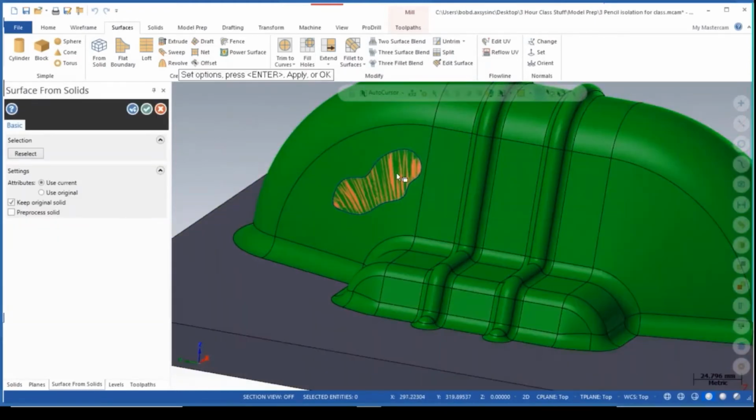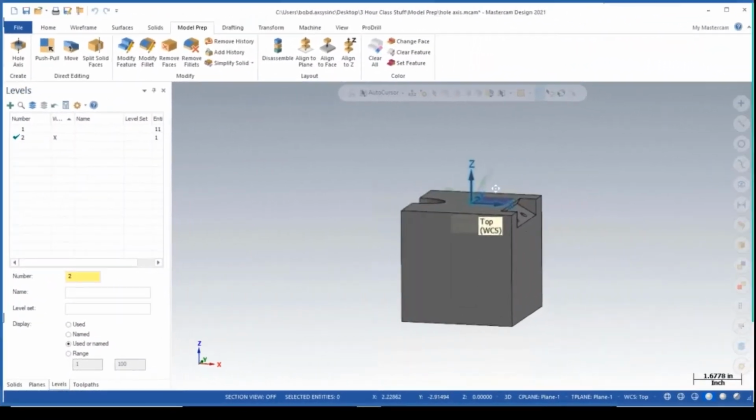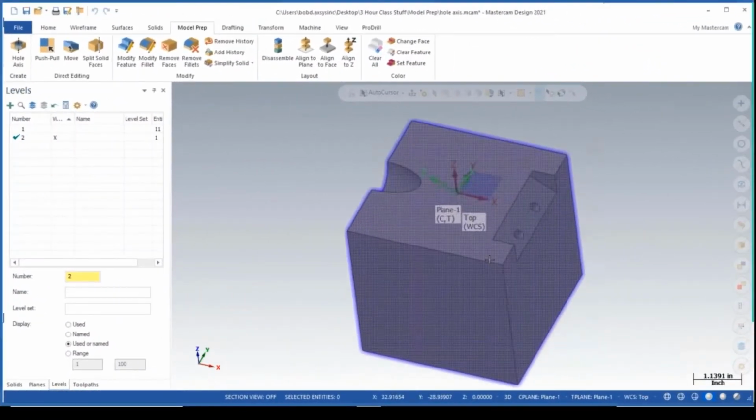And in my tool paths, if I had a machine loaded for my stock model, I could select just that surface, puff it out to represent the welded area, and target my tool path just to that area. It's a very handy function, because I can use the same tool path that I finished this with and just target that area. So at the end of that machining process, because it's essentially the same tool path, you virtually won't see any blend here.